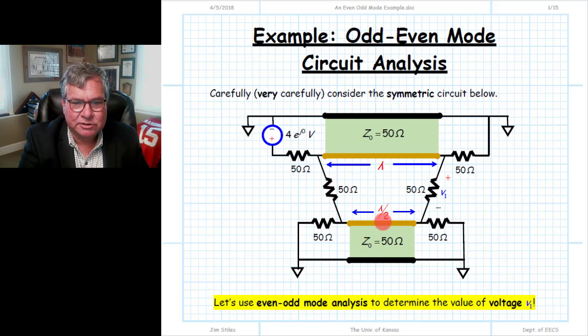What we've done here is essentially taking these two structures and we've made a 4-port device. Port 1, port 2, port 3, port 4. And then we've connected matched, quote-unquote, matched loads to 3 of those ports and connected this matched source to the first port here. And so we have a source, it provides energy into the system, and we'll find we get voltage and currents at every location within the circuit.